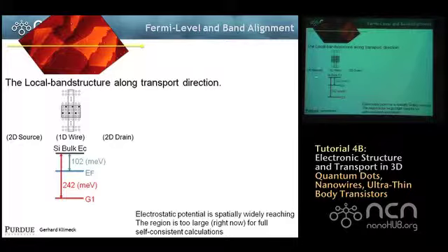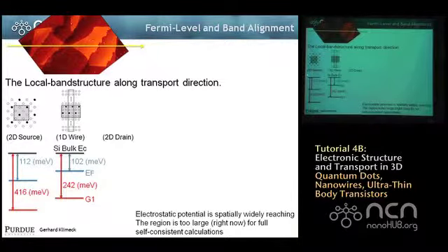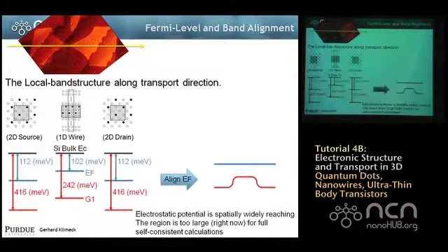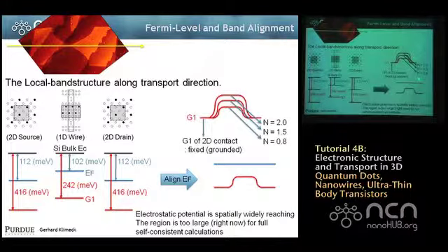And now we're connecting that to a source along this direction. This wire is connected to some source on the left and the right, and its energies are such that we normalize to the silicon bulk edge. The Fermi level is slightly different, and the bands are slightly different. And in equilibrium, of course, this stuff has to align, meaning the Fermi level needs to be flat, so you build in a potential. Okay? So you have a big contact that has a certain Fermi level and band edges, and you have a central region that has a Fermi level and band edges, and they're going to align if this is to remain charge neutral. And then you can ask yourself, can you modulate this barrier height?